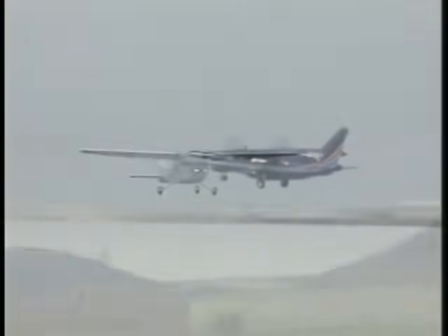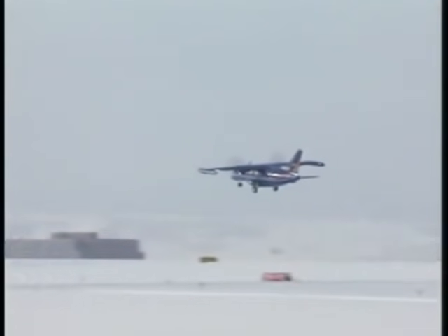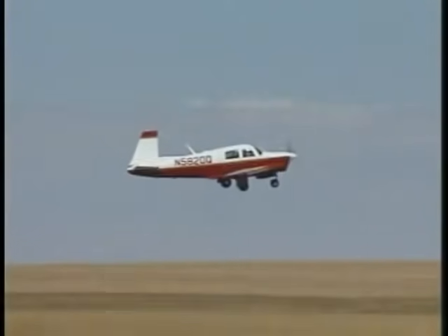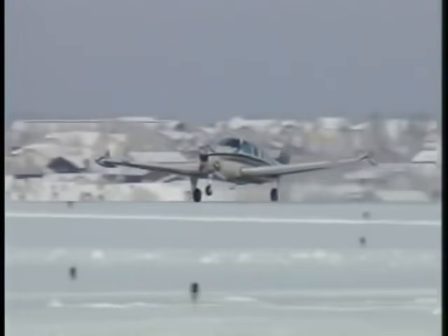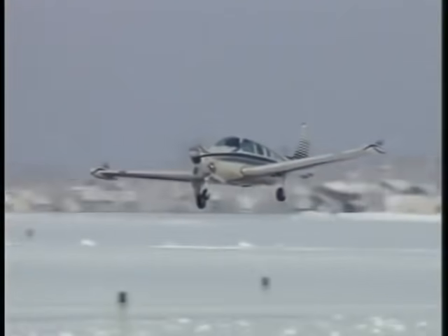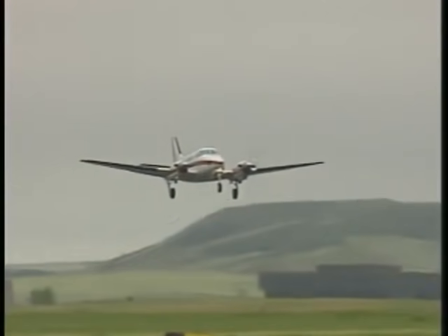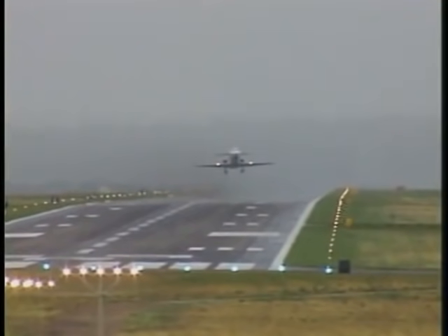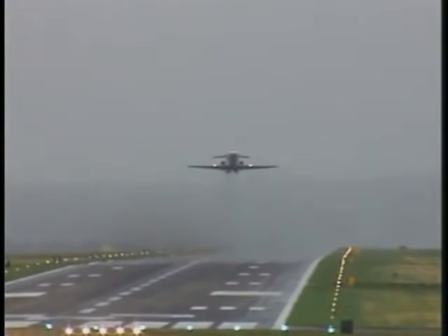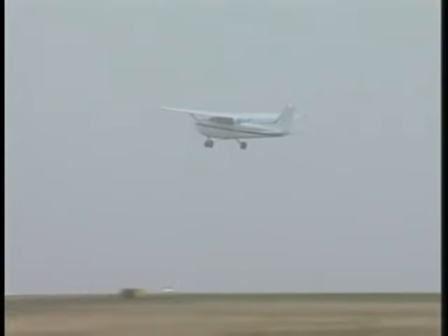To expedite an orderly and safe flow of IFR departures at busy terminal areas, Instrument Departure Procedures, or DPs, were created. These procedures and charts simplify departure for you and controllers, provide a transition between the airport and en route structure, as well as reduce frequency congestion. For example, prior to DPs, a clearance might have sounded like this.